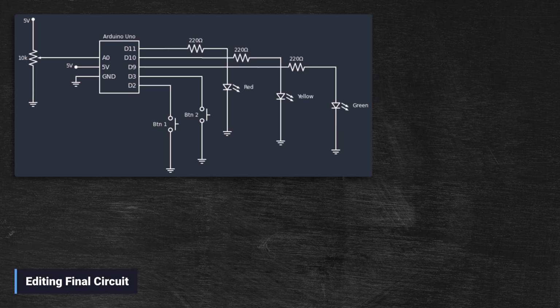This is the edited final circuit. We aren't just making LEDs flash. We are building a modular system. We will create a traffic light class that manages 3 LEDs and transitions between states: red, green, and yellow. We will also integrate a potentiometer to control the brightness of the LEDs in real time using pulse width modulation, all while keeping our code clean and object-oriented.